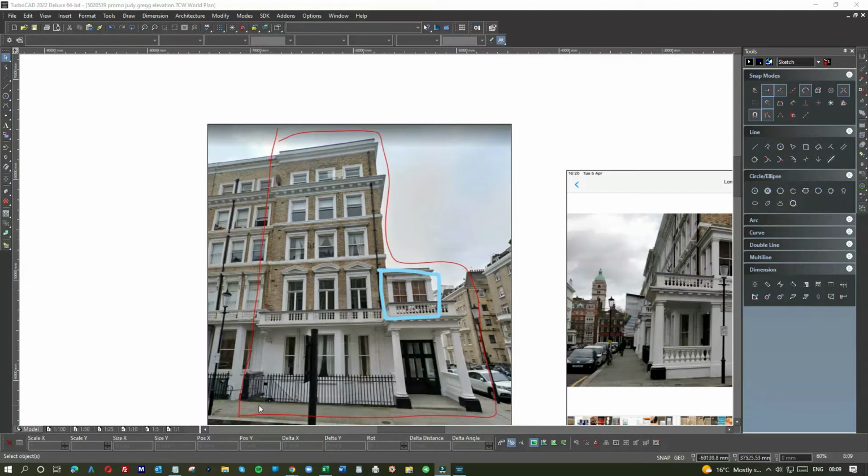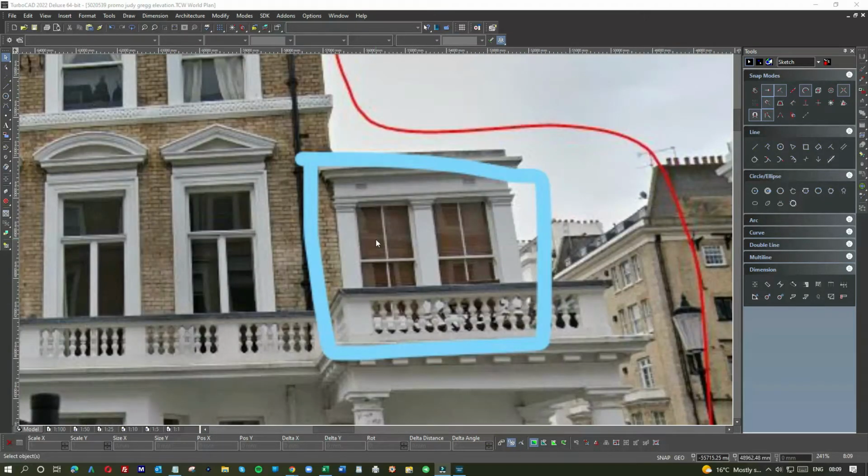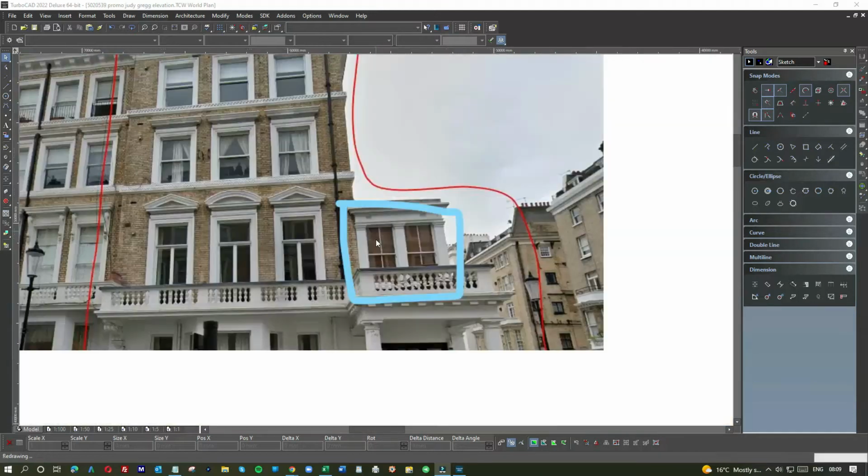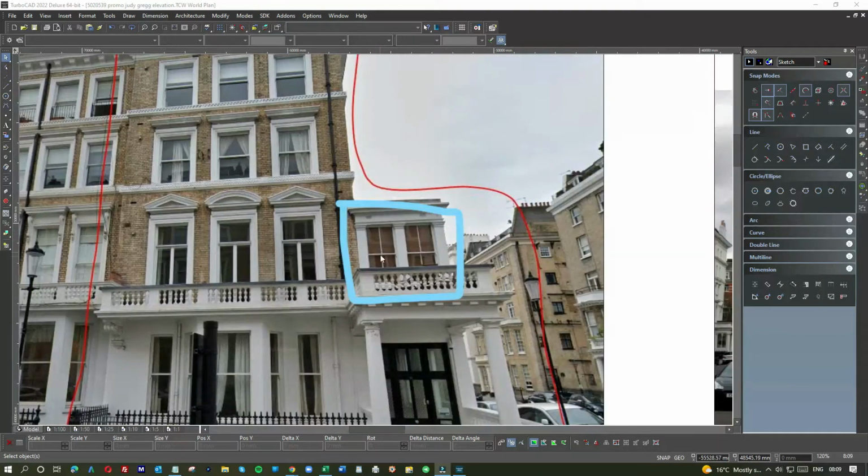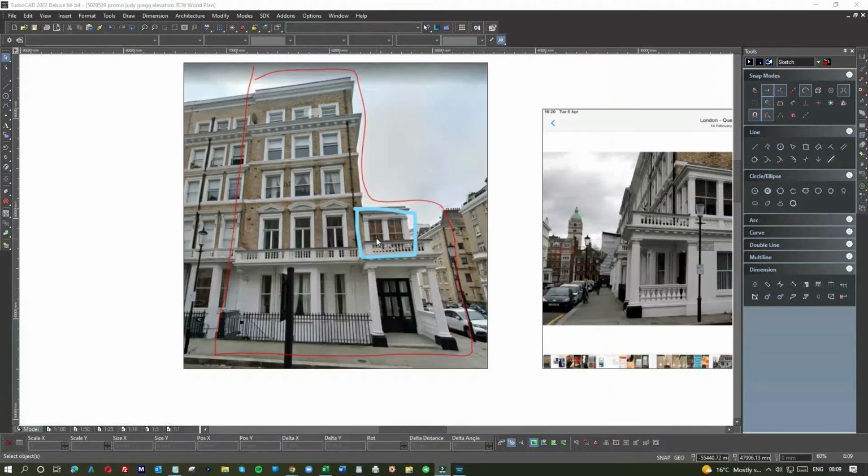for the entire building. So if you just want to change 1 window here, and when I say change, it's not like you're putting in double glazing or UPVC, and it wouldn't be allowed to do that. To change it from single glazing to double glazing, but basically doing exactly the same like-for-like timber sash window, you need a planning application, and you also need to submit profiles of the new windows, etc., so that they can approve.